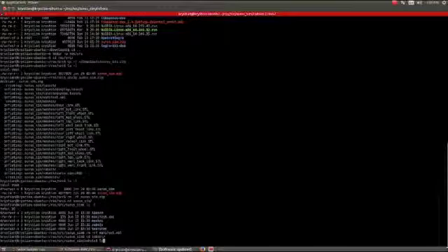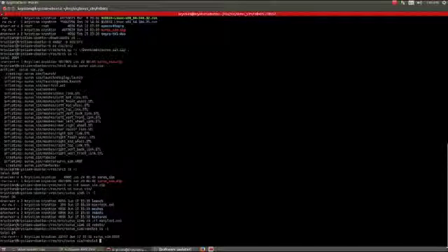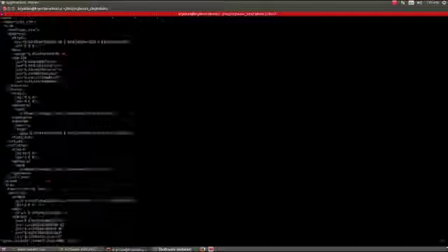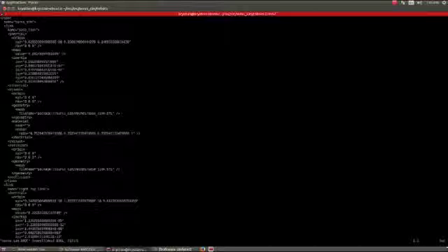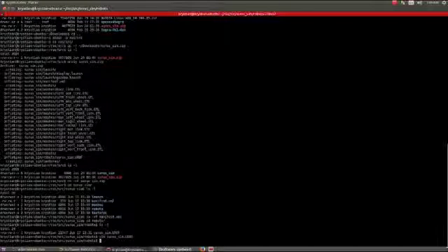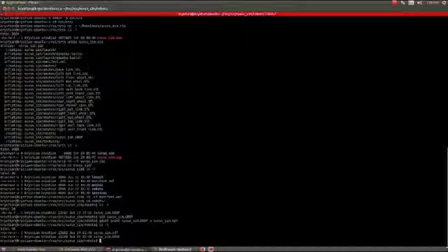If you go into the robots folder, you'll see that the URDF file from the exporter is here, and if you open it up, these are going to be all the contents for the different linkages, the different joints, and inertia parameters, mass values, and so on. So now what we want to do, as we explained earlier, is that the 5-bar linkage is going to be a graph-like structure. We're going to need to turn this URDF file into an SDF format. The way that we do that is we do gz sdf print of the URDF file, and then we want to output the name of our SDF. You can have it the same name, just a different file extension. So now you should see that the .sdf version of the file is there.